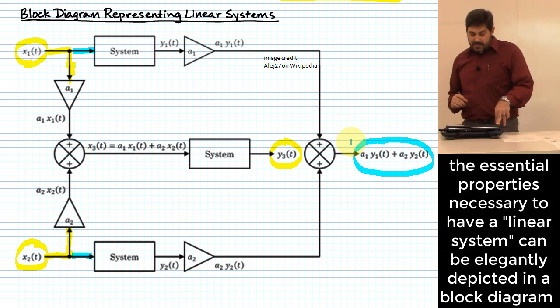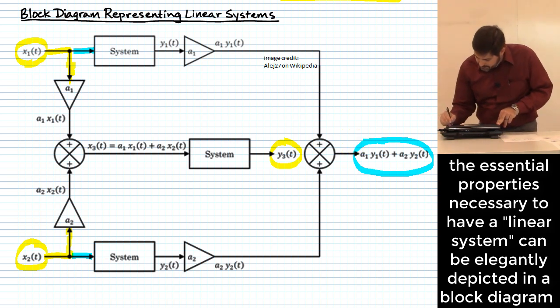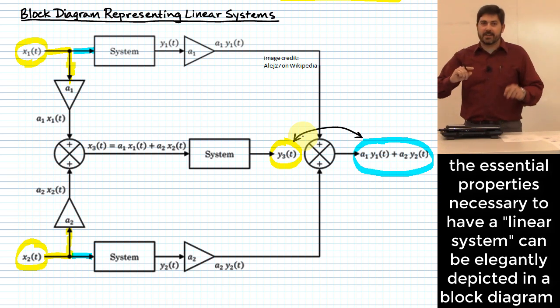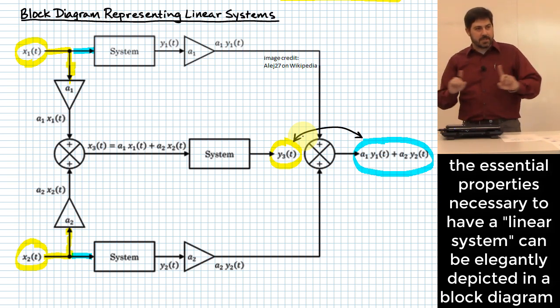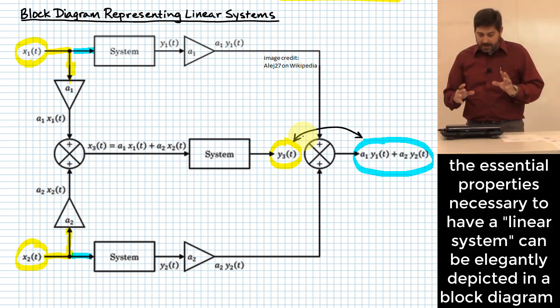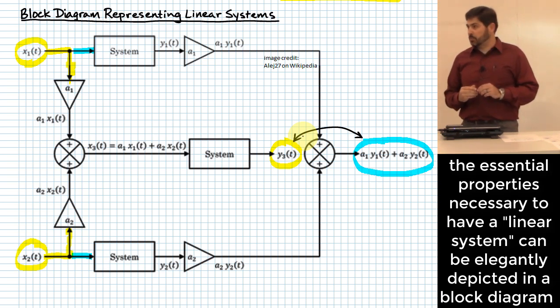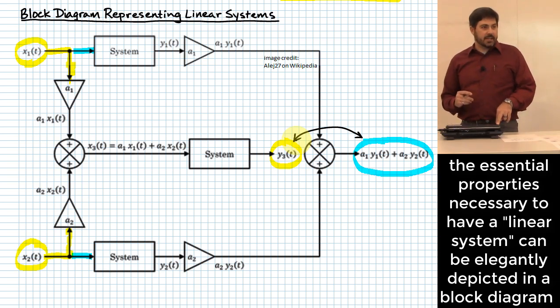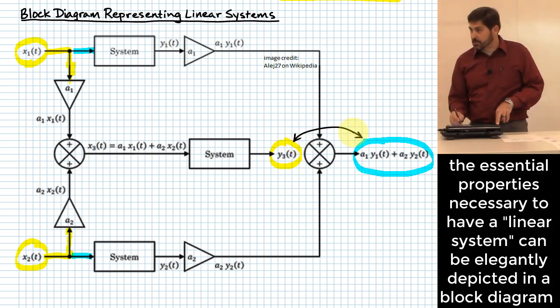If you have a linear system, then these two signals will always be the same, regardless of what your inputs are. Does that make sense? This is the application of homogeneity and additivity put together into one thing, describing how linear systems work. It's that those two outputs, whether you do it one way or the other, give you the same result.